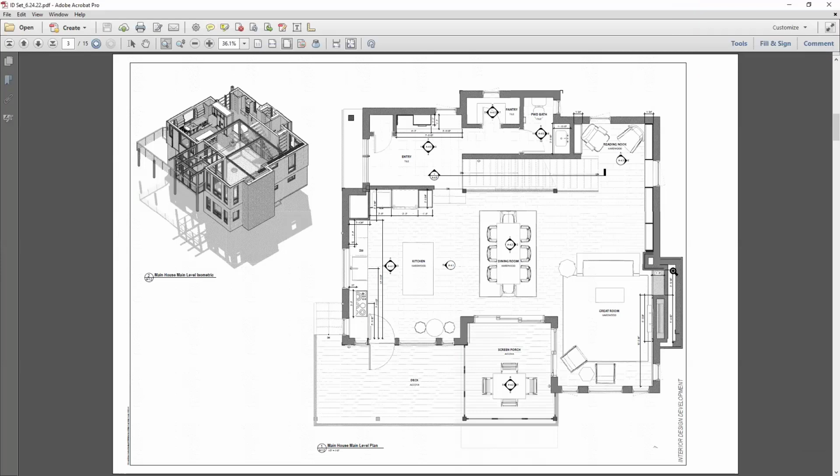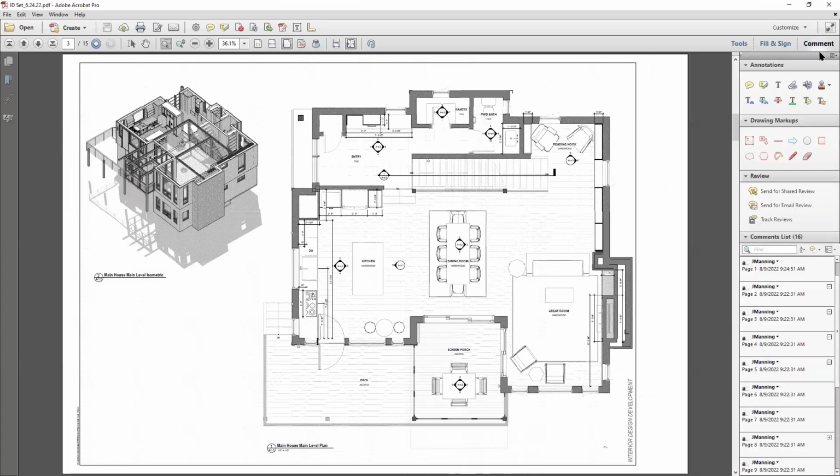I do have, just to the left of your cursor, that's also a bookcase area with a soffit. So if that is able to connect to the other row of bookcases, that soffit will get you over to where the window starts, which is where the glulam beam stops us from continuing. That might be as far as we can get without a very low soffit that would go under the glulam beam there.